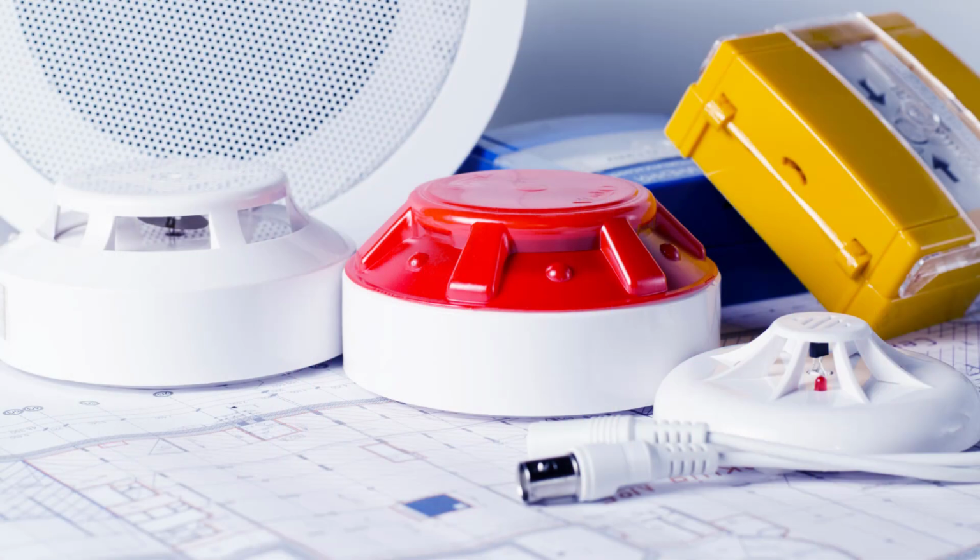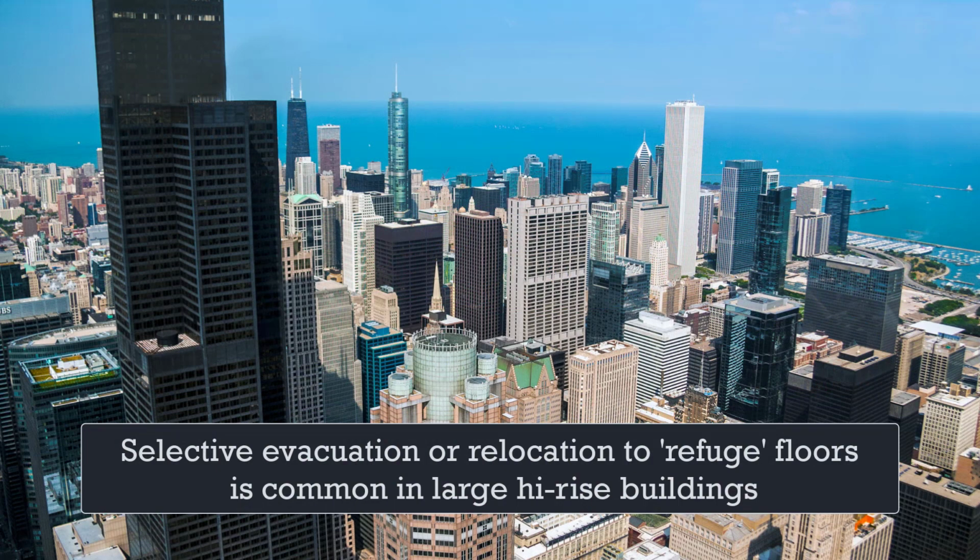Pre-inspection and testing is particularly important in larger properties having an abundance of fire alarm system devices and more complex high-rise evacuation system procedures. For example, large high-rise properties incorporating a fire evacuation procedure relocating occupants from the fire incident floor and adjacent floors above and below require specific fire alarm activation and sequencing to test and practice this procedure.